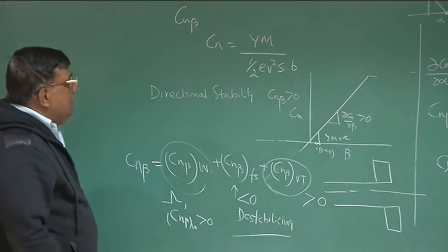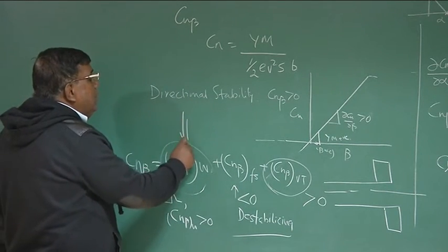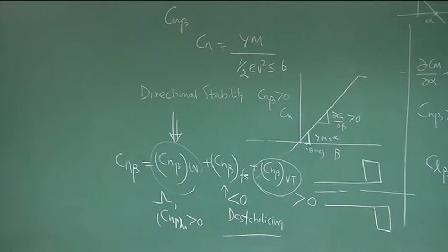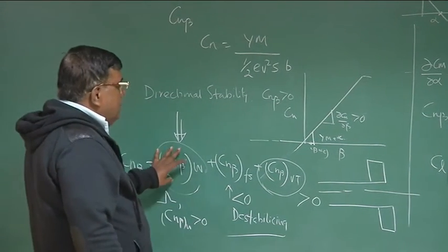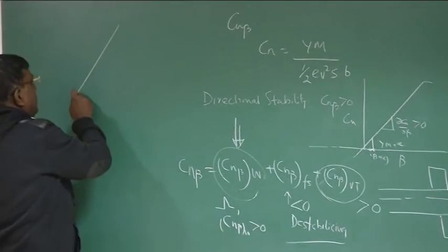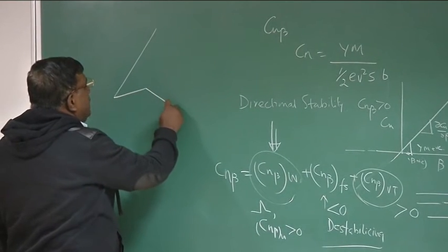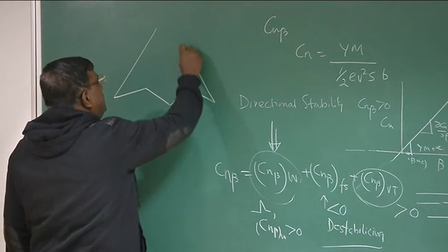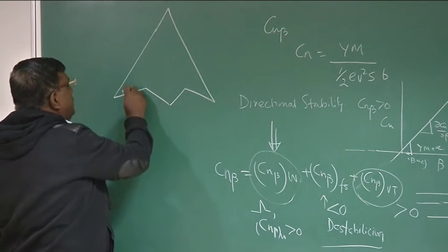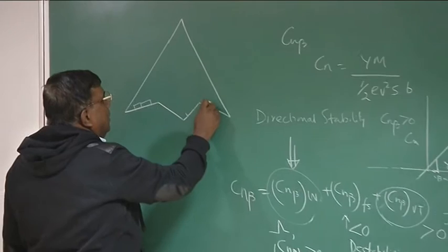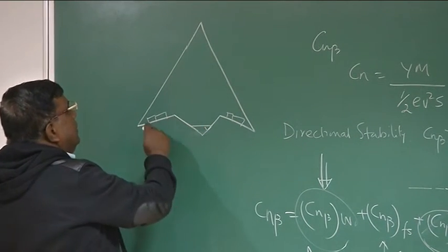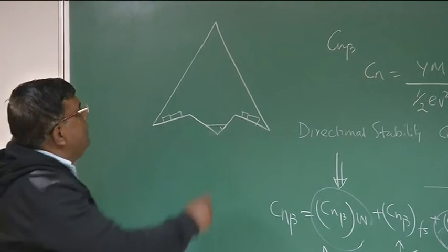But you could see that if you give a sweep, you can get it from the wing also. So nothing very big claim. You can get Cn beta positive, you can stabilize directionally by making the wing have a sweep. That is why in vertical tailless airplanes, whatever you might have seen, stealth aircraft, B-2 bomber type, there is no vertical tail. There are control surfaces here, somewhere here also something is there, right? It doesn't have a vertical tail, but it has a large sweep.